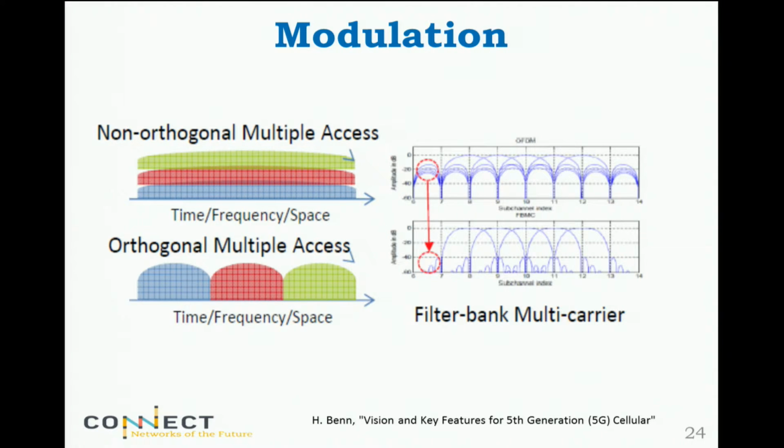So what does it mean? It means that with OFDM, you don't really filter. In time, you basically have a rectangle. That's the pulse shape you use in OFDM. What this implies, if you take the Fourier transform, is that it decays slowly. Actually, it decays with 1/f, so it's a sinc. It does decay fairly slowly. Then, if you remember from your DSP classes or basic digital communications classes, you probably remember something like this. So anybody that has some idea...